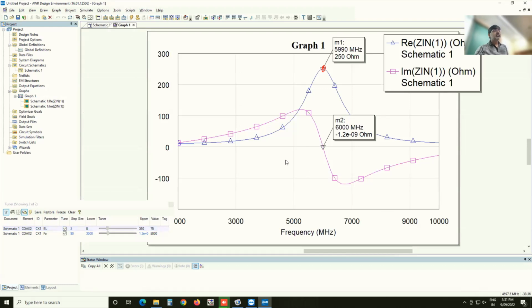So why is this kind of circuit useful? Because it allows you to change the impedance from one value to the other, and that can come in handy when you're trying to match certain things, or you're trying to deliver power from a source which maybe has a characteristic impedance of 50 ohms, but you want to deliver power to a load which has 10 ohms, and you want to maximize that power delivery.